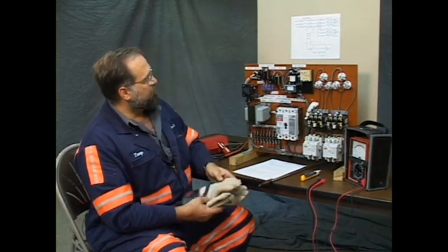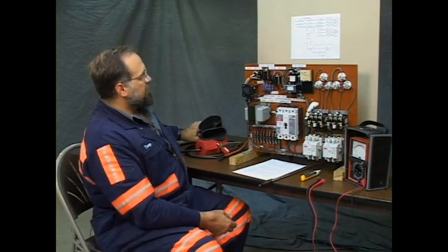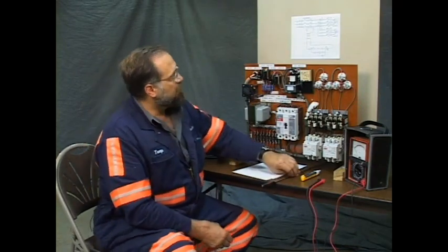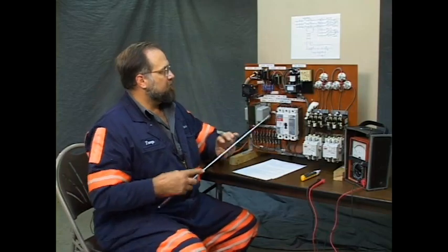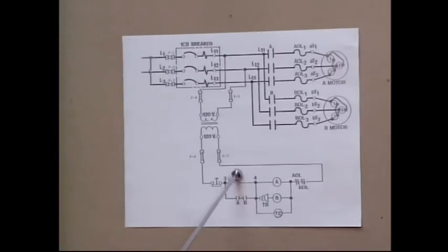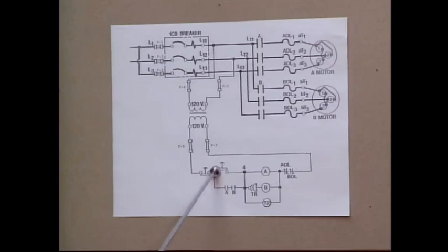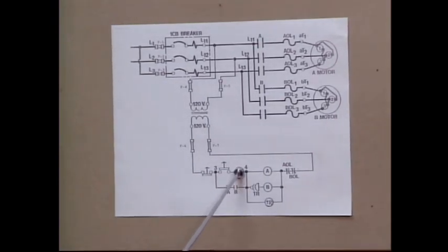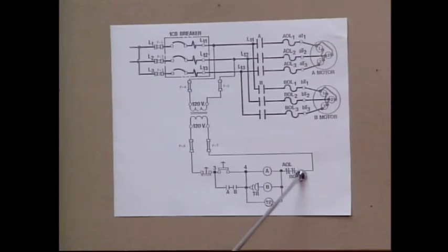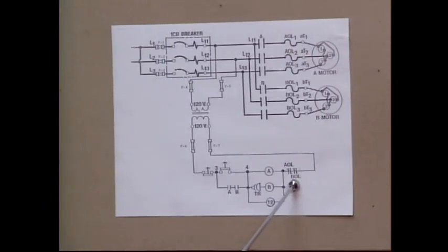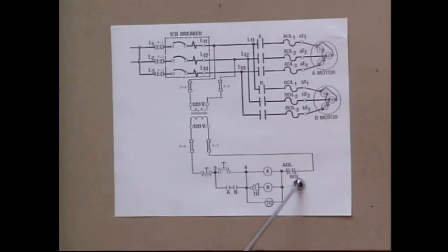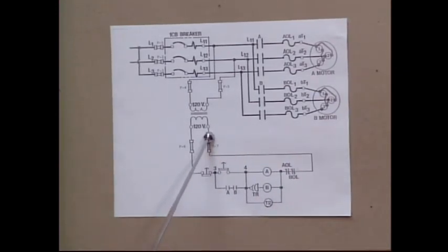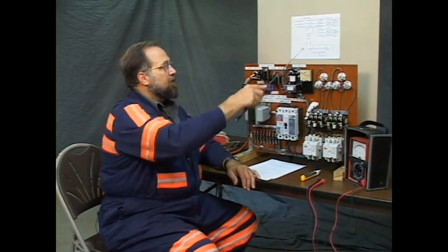Now our problem states that the A contactor is not closing. And when we operated it, it truly was not. So when you press the start switch, you connect one side of the control transformer, the X1 side, through the start switch to the A coil, through the normally closed A overload micro switch through the normally closed B overload micro switch to complete the circuit to the X2 of the control transformer. Well, that didn't happen.